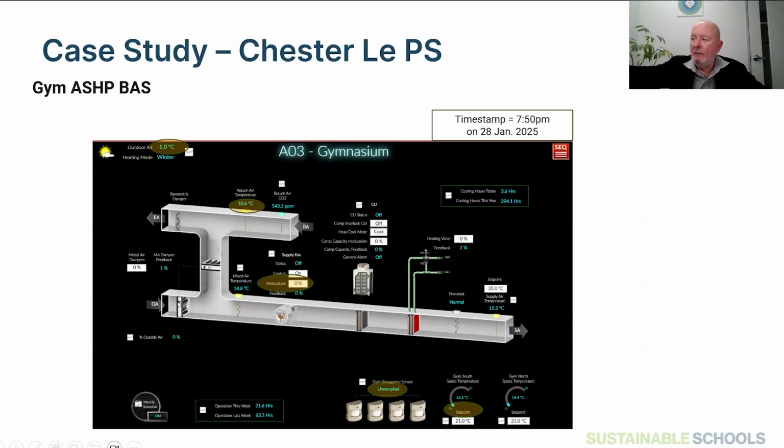The Mark picked up, do you see that the return air temperature at the top is at 10.6 degrees Celsius? Obviously the fan's not running, but that would suggest there's outside air leaking in through the relief air dampers or the outside air dampers, or both, depending on where the sensor's located. It'd be good to have the commissioning folks take a look at that, say, are the dampers closing nice and tight? But we love that you've got the occupancy sensors in there.